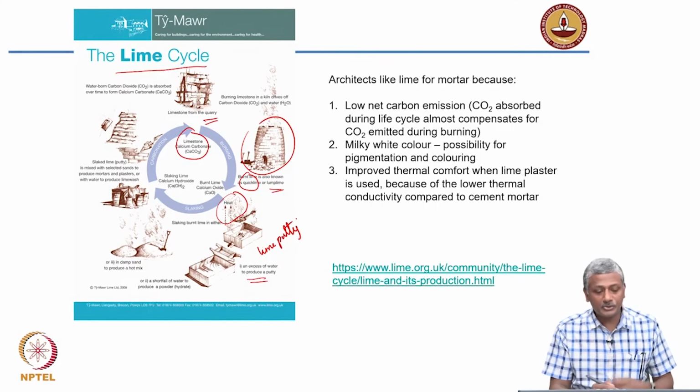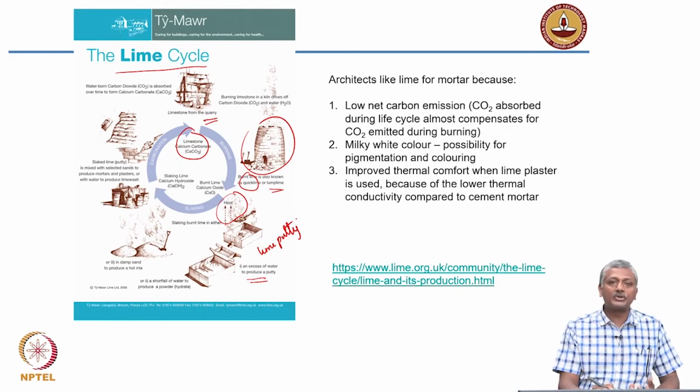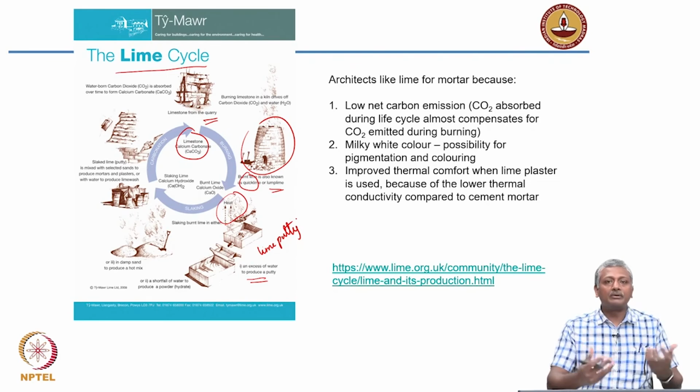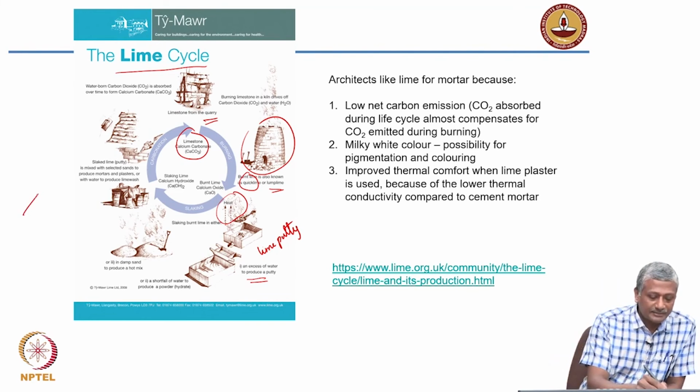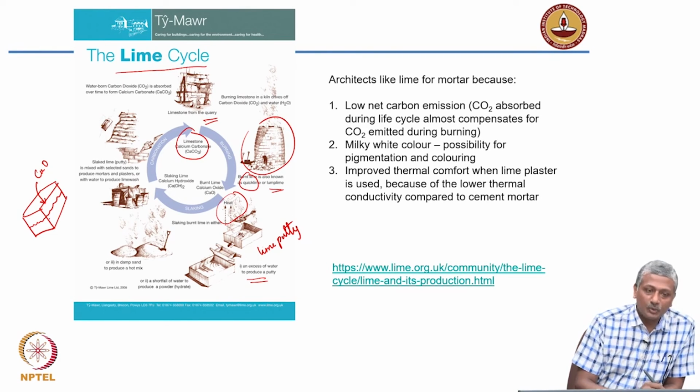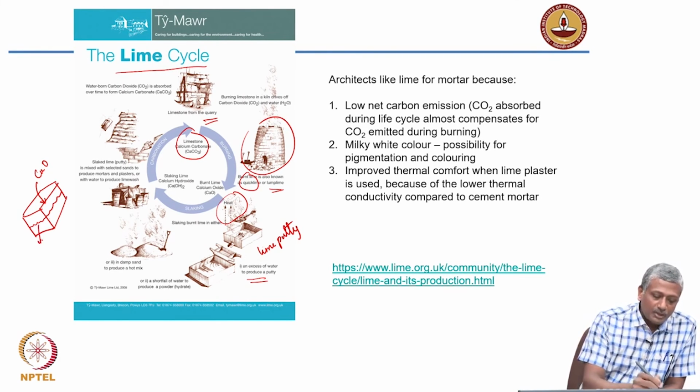So again, just to tell you a little bit more about the slaking process. In most large lime producing facilities, what you will have is these tanks. You will have rectangular tanks. You basically fill them up with water, and then you dump your quicklime into this water. With time, if you look at what happens here, I'll just draw the cross section.